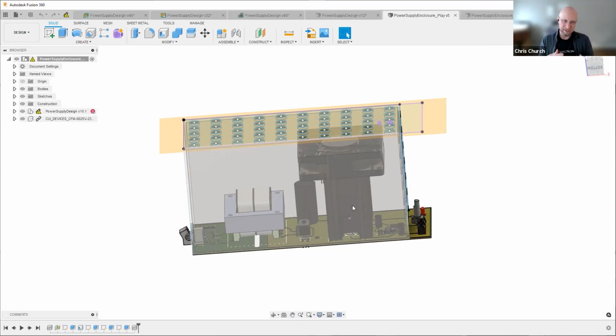And you have to really reason about how all that's going to go together, and think about where the design issues and interfaces are going to be. That can be really challenging. A lot of times what we'll have to do is what we call a first article build, which can be very costly, because we have to get a small number of these enclosures and all the different components and start trying to fit them together and seeing where our process issues are going to be. But with this 3D model, this is really nice. This really helps us out.